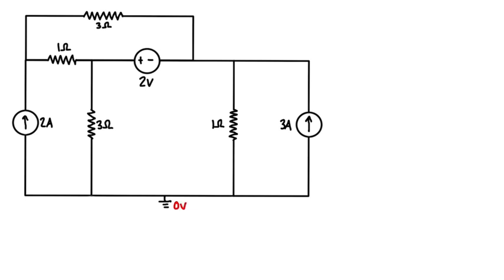And then up here on this node, let's call it node A. This one will be called node B, and this node here is going to be called node C. So we have 3 unknown nodes, and we're going to need 3 equations. The first equation that's going to be really easy for us is just doing KCL at node A. And then we're going to need to identify our supernode, and then we'll do KCL at the supernode, and also do our supernode equation.